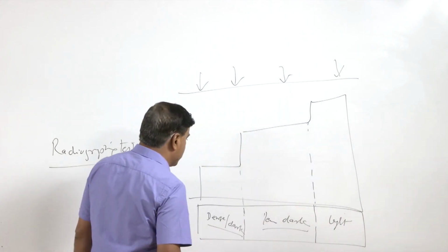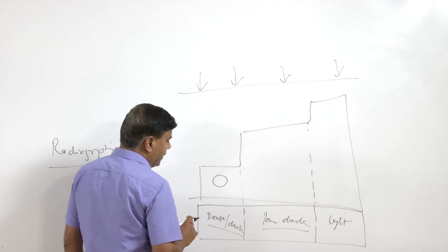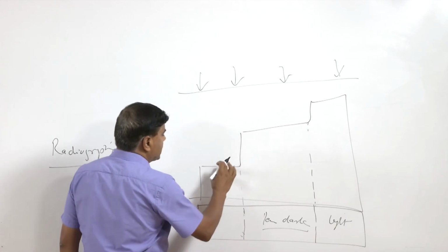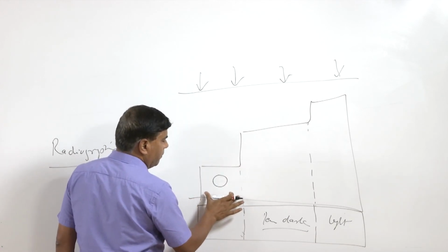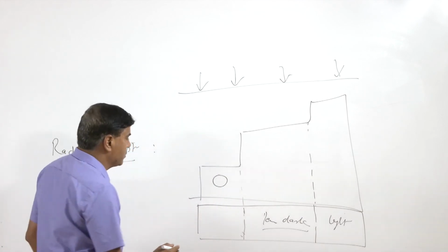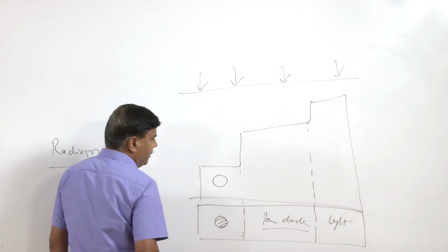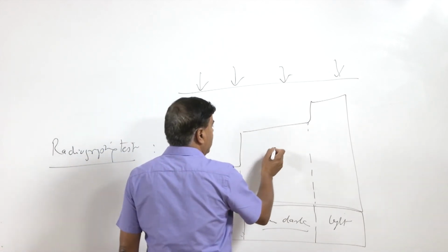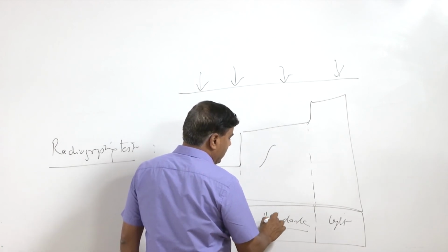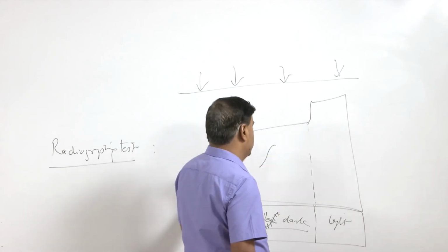As and when we come across a particular kind of defect like this pore, this is the area where rays will be absorbed and this is the zone where no rays will be absorbed, so this location will look dark. Similarly, if there is a crack, we will see one dark line like this, indicating the possibility of a defect in the component.